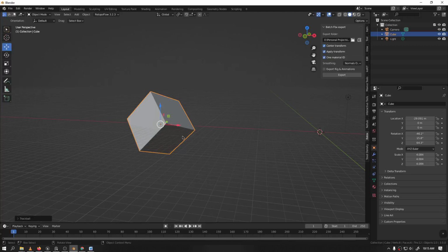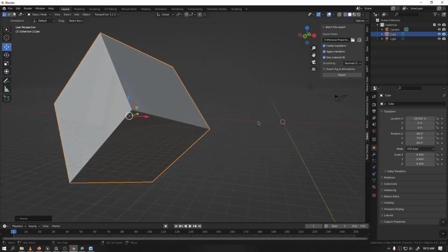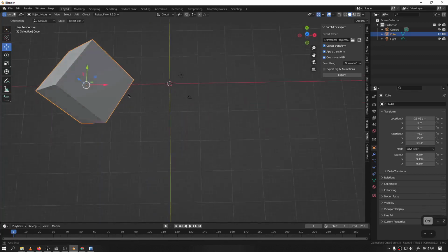And you see that because we have scaled the object, rotated and so on, the scale has been ruined and you need to fix it. And one way is to hit apply all, and this one basically does that. It sets everything to default so that the default proportions become all one. And it's good for when you export into other applications, the transform will be alright.